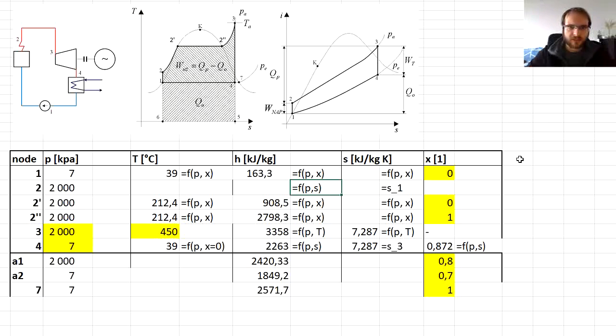If we don't have these functions, we will use the first law of thermodynamics and the fact that we have a liquid, which in the ideal case is incompressible, but still we will need to use one more parameter, and that will be density. And for the density, you can use some steam tables or things like that, from which we would get the value of the density as 992.6 kilogram per cubic meter.